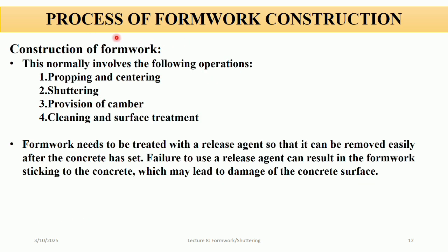Now let's discuss the process of formwork construction. So this normally involves the following operations. Number first, propping and centering. So propping and centering provide temporary support to hold the formwork in place until the concrete sets. This ensures the formwork remains stable and secure.